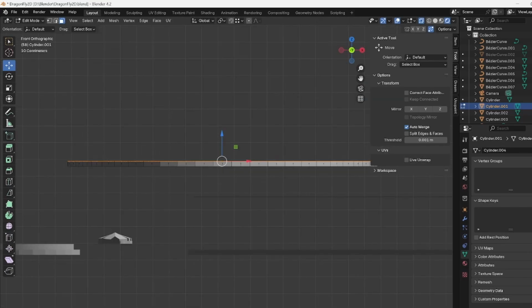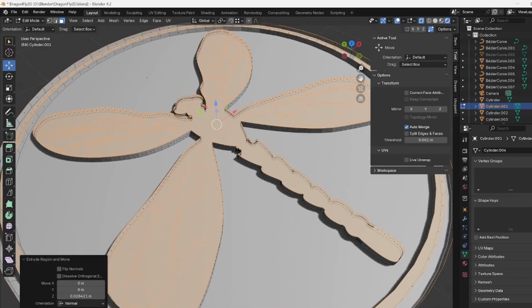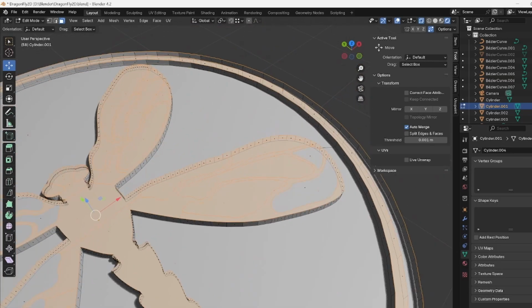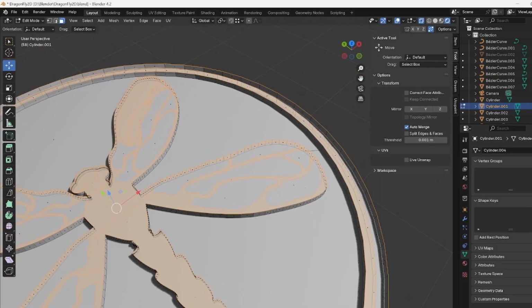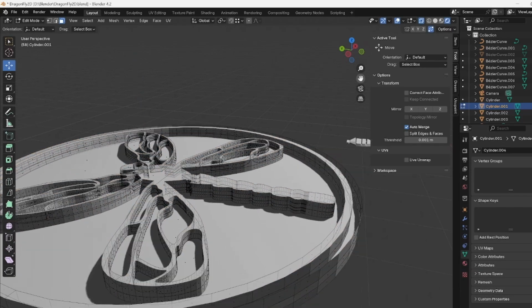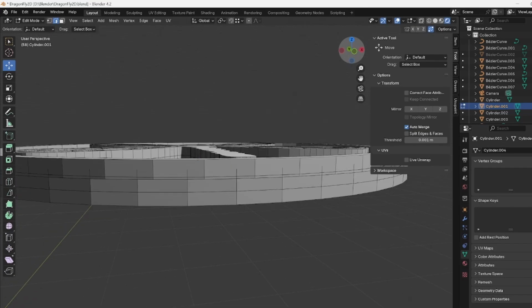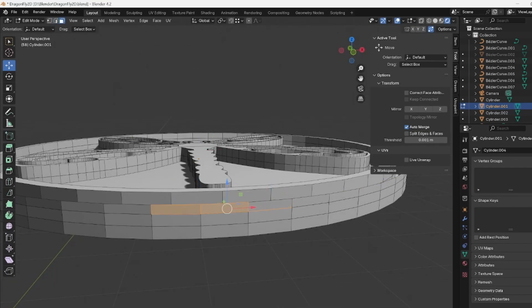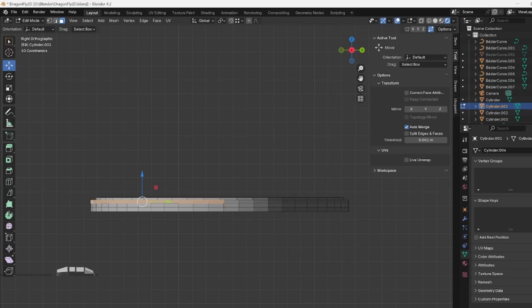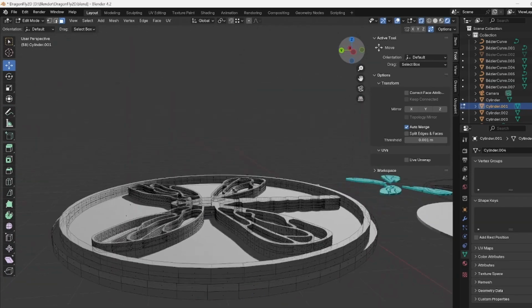All right, here we go. And I'm just going to raise this up, and this will create a much more efficient model for slicing and printing. If I raise these up one layer at a time, I can set the printing colors up like a layer cake in the slicer in Bambu Studio. It'll create a much easier setup for the colors and probably a lot less wear and tear on the printer, zigzagging around and swapping out colors, and a lot of that waste that comes out of the back end.